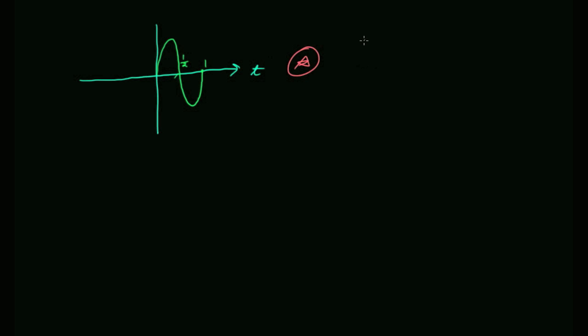We know the Fourier transform for both of them. The Fourier transform of the sine is just going to be an impulse. And the Fourier transform of the square wave is going to be a sinc. So if we multiply them in the frequency domain, it's just a shifted sinc function. Exactly. Well, but this is a single period. I'm not talking about an infinite cosine. Oh, okay. Although we could do the infinite cosine case.